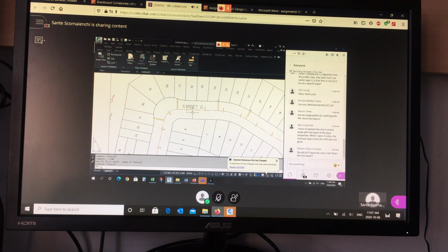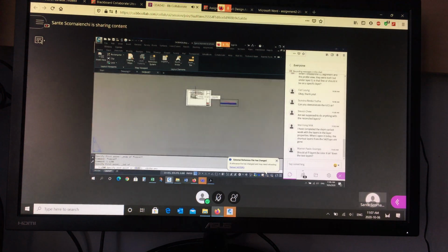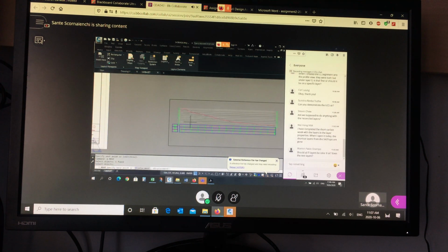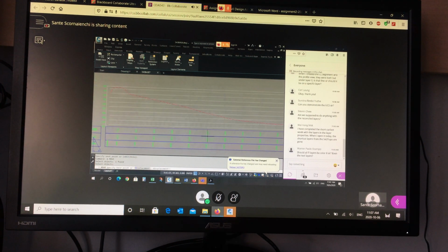So I want to draw a line in paper space from this intersection, and I'm going to turn my ortho on and go straight down. So there's where station 100 is. Then I'm going to move the viewport, again, all in paper space, snap to the line for 100, which is right here, station 100, anywhere on this line, so I'm going to use the top endpoint.